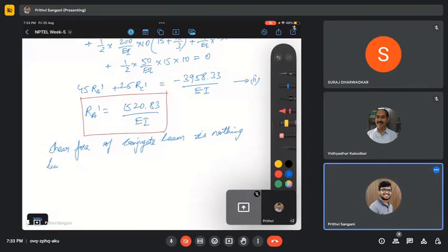Okay. So now we have, if shear force is positive, right? So right now again the positive is something like this. So we have assumed RA to be negative downwards, right? So now we got it as positive. So if this is positive, which is downwards, right? If shear force is something downwards, then we have slope which is clockwise.